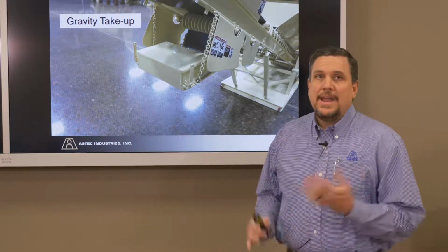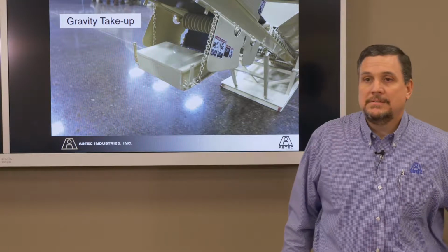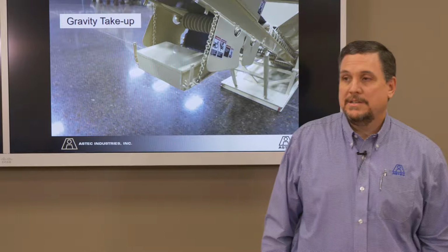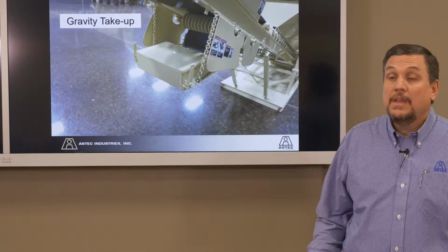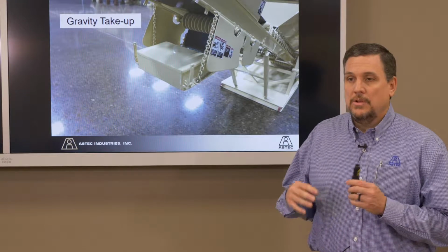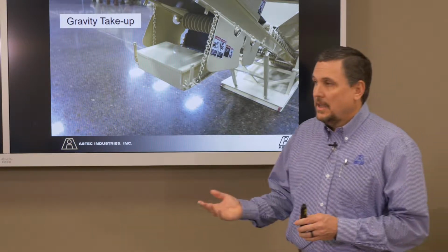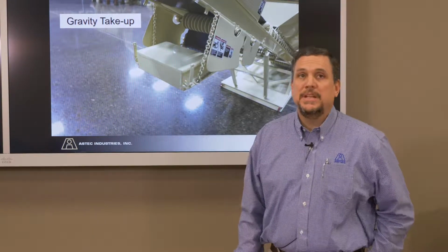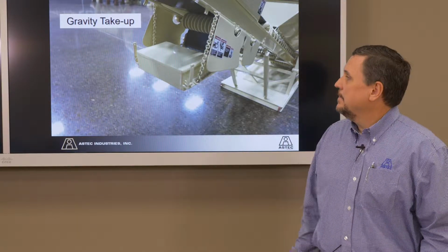Some people may ask, well, hey, I don't have a gravity take-up on my incline belt with my weigh belt. Is that going to give me a problem? It very well could, but sometimes as long as you keep maintenance up well and you take care of your belt, you can do it without a gravity take-up, but it is much, much better to have the gravity take-up in place.